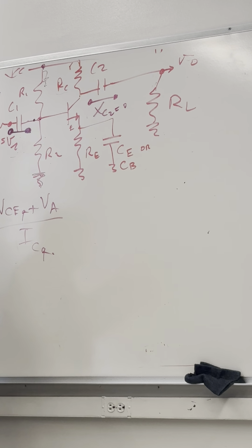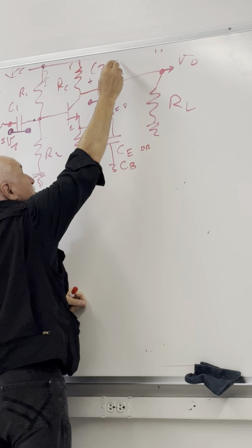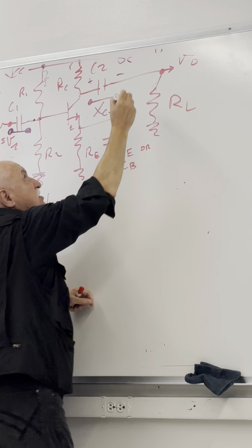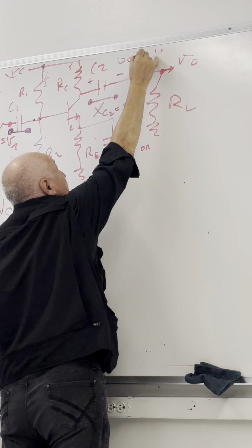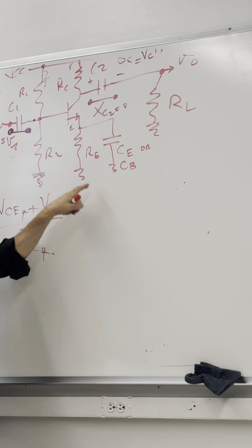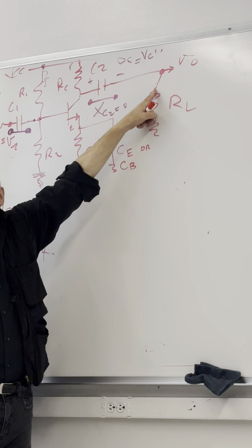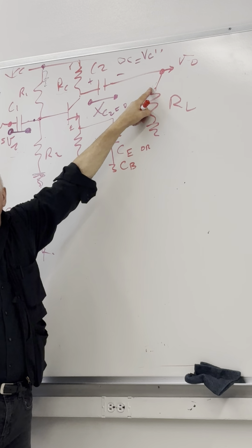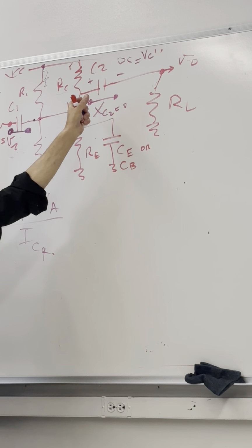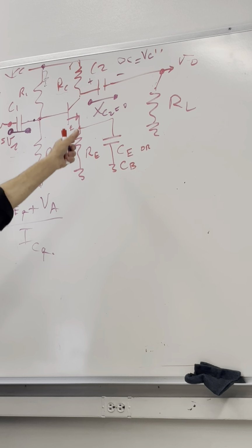At high frequency, there is no voltage drop. So you're assuming the capacitor is large. But I tell you what, there's a DC voltage on it. The DC is equal to V of the C, whatever the DC voltage is there with respect to the ground. DC voltage here is 0 because it's the load. There's no DC voltage over there. So this capacitor, gentlemen, acts like a battery.